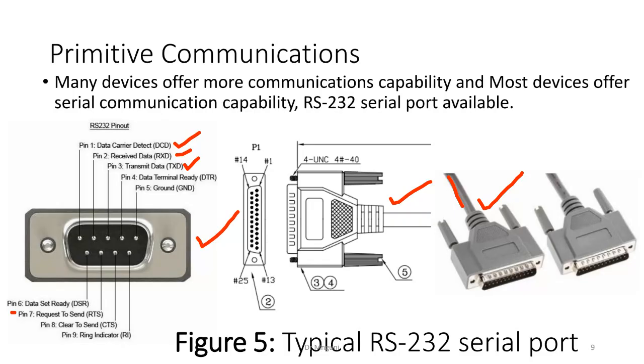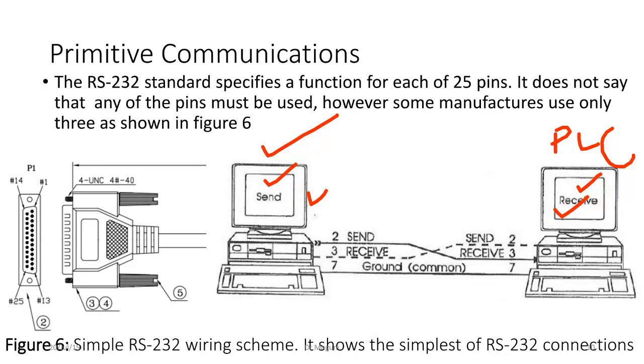So now, coming back here, we'll introduce a fourth one, which will be the one doing what we call handshaking. And what is this fourth pin doing? It will create a system so that the second device sees the information that is sent, and then it tells the sender, yes, I am clear and ready, please send.